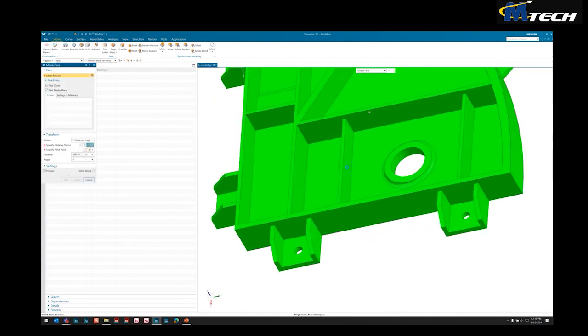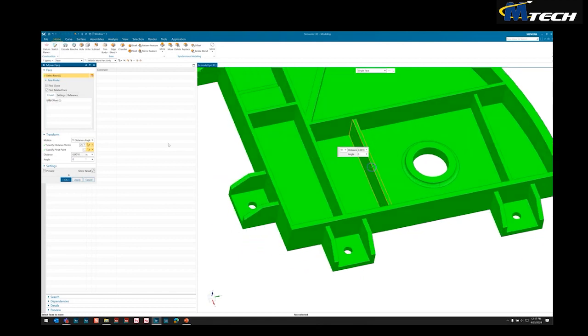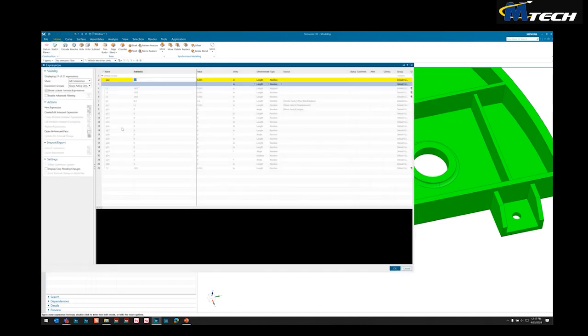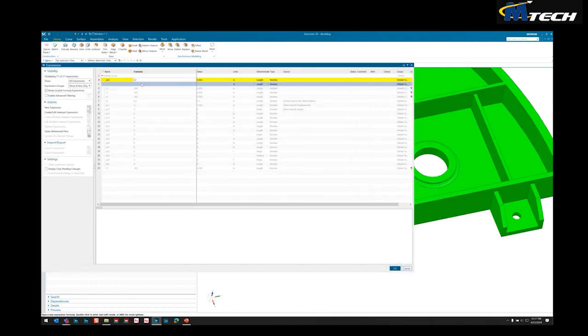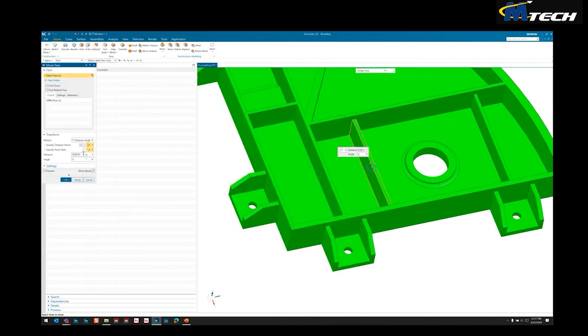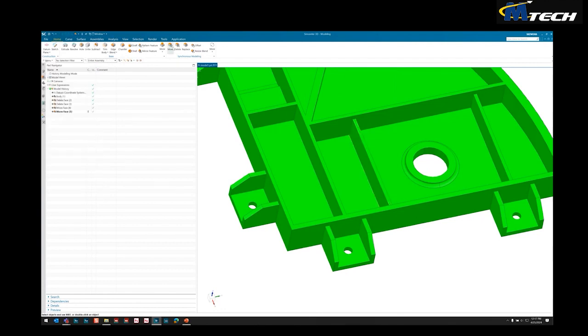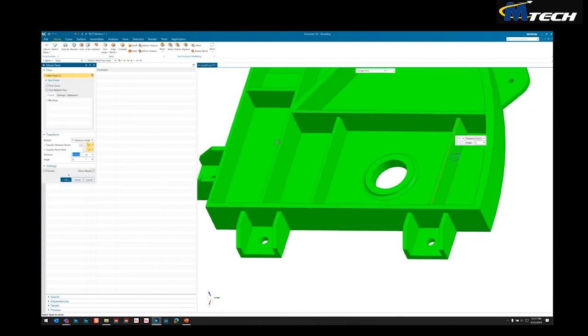The second, we'll do this 2 more times. It allows us to automatically pick other faces, just saving time in our workflow. We'll set that equal to our L2 distance and hit OK. And then we'll move our last face, pick our offsets, and set that equal to L3.